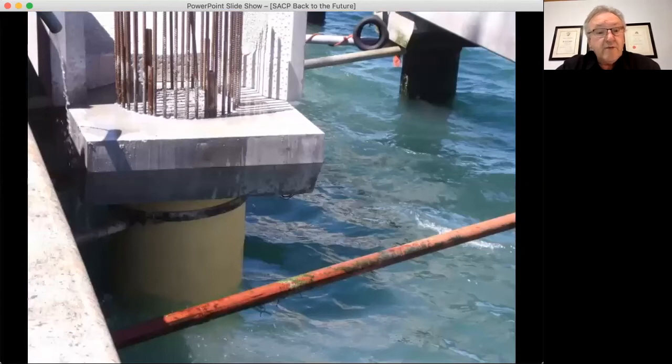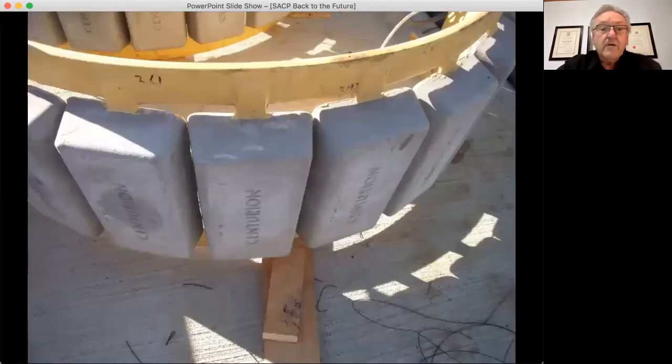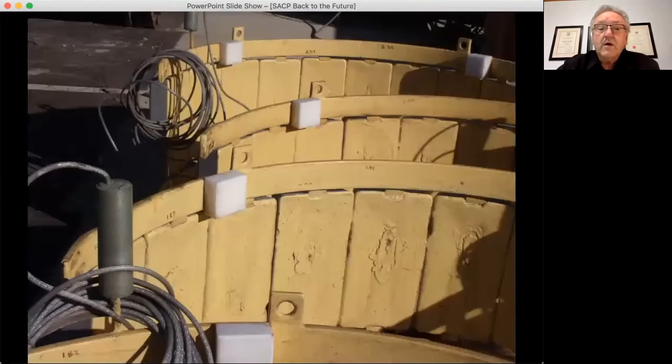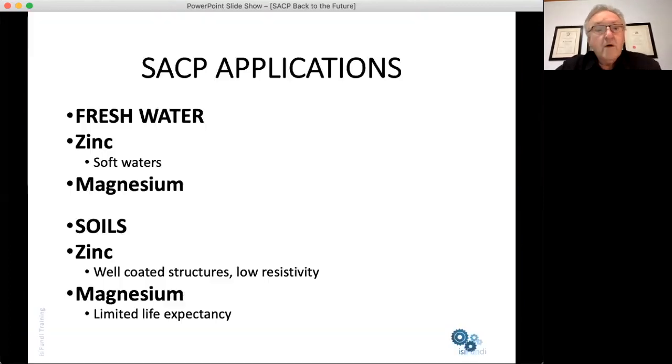This jetty is being expanded, and this tubular pile that you can see over here is coated against corrosion and will also be receiving cathodic protection. The cathodic protection anodes for that particular structure were mounted on a bracelet, and the internal of the bracelet was coated in order to extend the life of the anodes. Having looked at the marine situation, what about the rest?